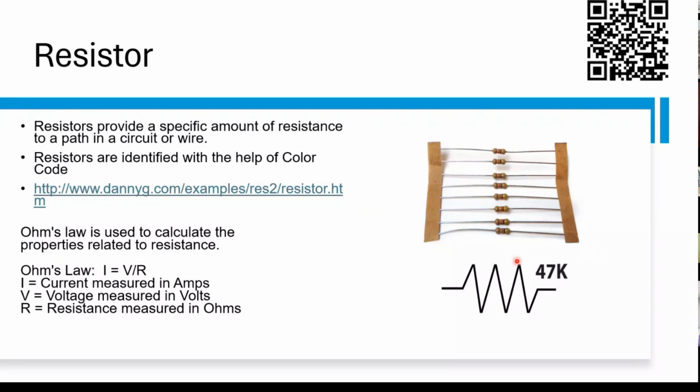Suppose I have a small LED. My image is visible. Can you see the LED on? Yes, sir. Okay. So if I connect this LED straight away to a battery, my power supply, this LED will burn out, in the sense it gets spoiled. So to limit the supply current that goes to this, we'll be using this resistor along with it.